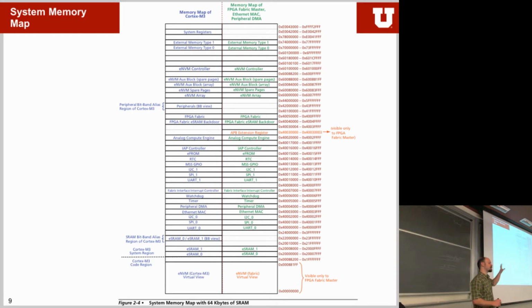Oftentimes they make the register maps such that you always have to write into something to clear a bit, or you read a bit to actually get the status out. You will see about it. Sometimes you have 3 registers to do operations on more or less the same background register that they're actually using. So for this case, if you want to clear one particular bit, you write it to one memory location. If you want to set one particular bit, you can write into a different memory location without having to change or touch or read out that particular register. Did that make sense, what I just said? If not, it's a very important concept.